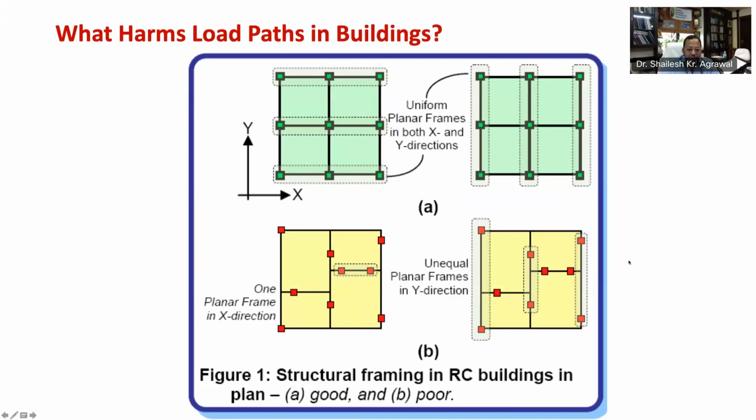Remember, as I told you in the previous tip, large detours in load paths result in stress concentration in the frame and in poor performance. This will happen with discontinuous frame lines and if beams frame into each other instead of columns.